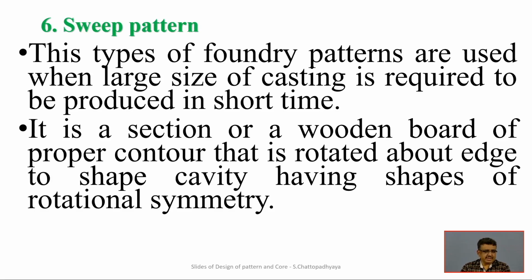So the next class of pattern will be the sweep pattern. These types of foundry patterns are used when large size castings are required. We don't want to make a large pattern, we want to make a small part of the pattern, and because of the symmetry we rotate, sweeping in order to generate that kind of cavity. It is a clever way of generating the cavity with a smaller part because of the symmetrical shape of the cavity.